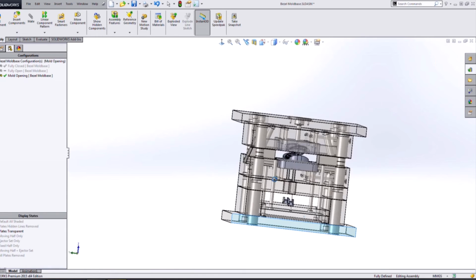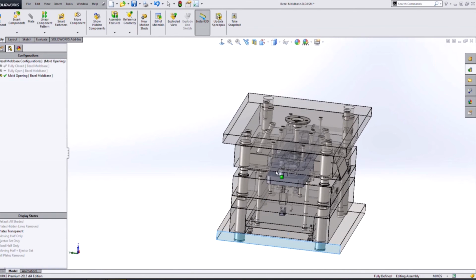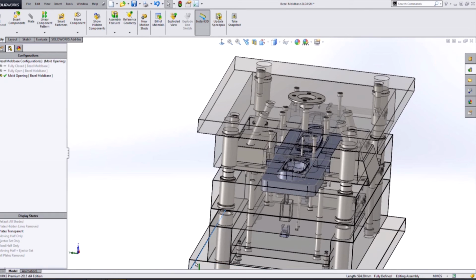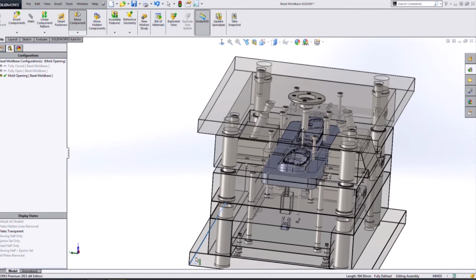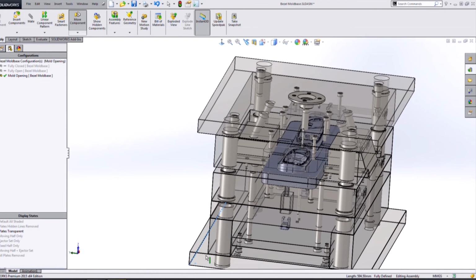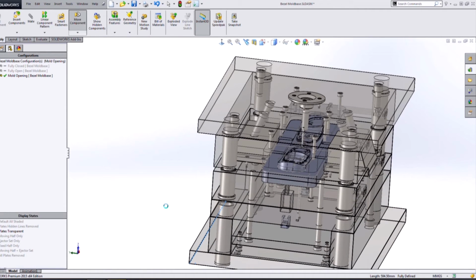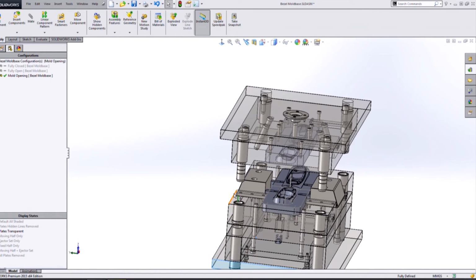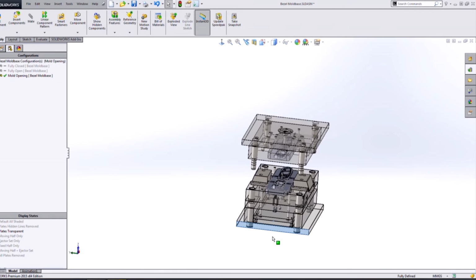And if we sort of angle ourselves so you can see the side cores here and repeat that motion, you can see how they follow along with the motion of those side releases. So if we slide this thing all the way down and open, what you can see then is just the ejector pin.